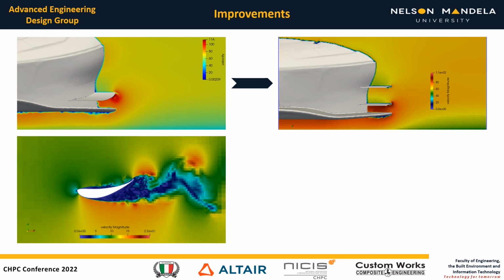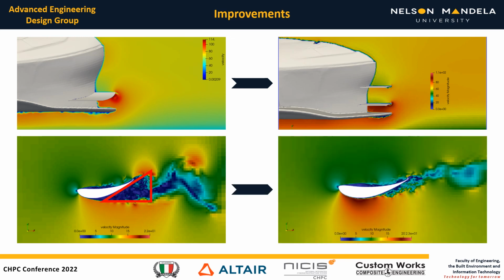I then optimized the angle of attack of the rear wing. I found that the original angle of attack of 9 degrees resulted in a large flow separation, and that an angle of 6 degrees was 140% more efficient. The next step in the research is to implement vortex generators on the roof to help reduce the drag.